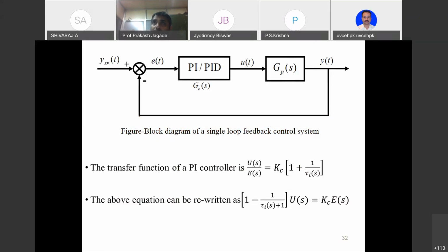What is more important here is that we have to satisfy the specification. The specification which I had chosen for the conical tank process is the settling time, or a closed loop time constant. At all operating points, what we want to satisfy is the desired closed loop time constant. In order to satisfy it, we modified the controller settings, that is, the integral gain.